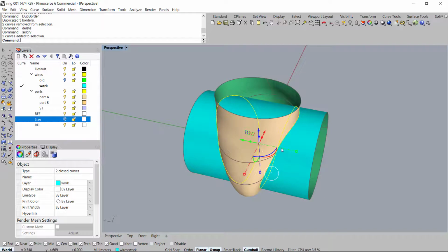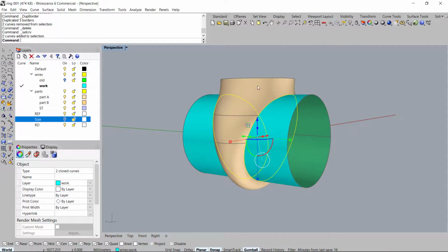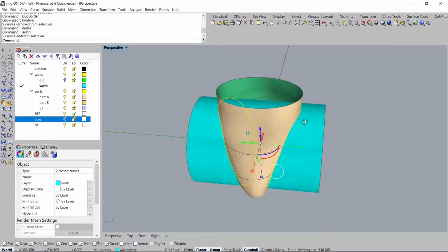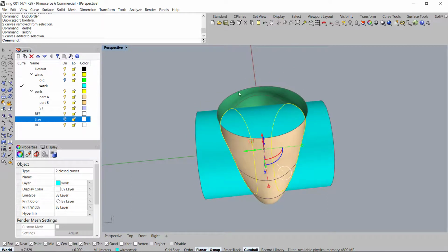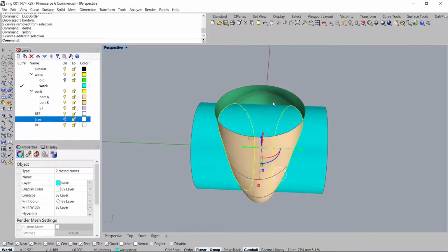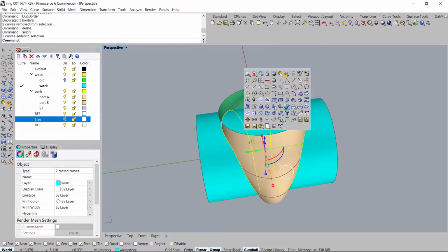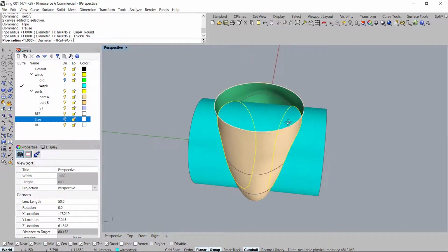So I told you before, or I don't know if I did, but I want to keep the thickness of the metal to be 1 or 0.8. So you kind of want to offset that finger border on the inside a little farther than the wall. So if I'm going with 1 or 0.8, go with something like 1.2 or 1 if you're using a 0.8 thickness. Alright, so I'm going to pipe it and make sure you're on radius, and we'll type in 1.2.